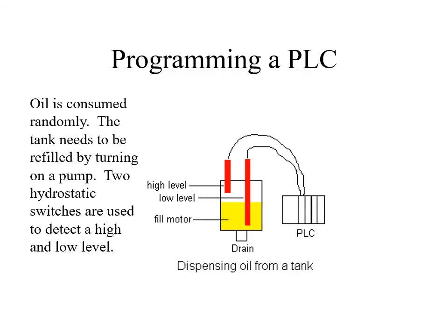And let's take a look at a real-world example, programming a PLC. Let's take a look at the situation. Oil is consumed randomly. The tank needs to be refilled by turning on a pump. Two hydrostatic switches are used to detect a high and low level for the oil.